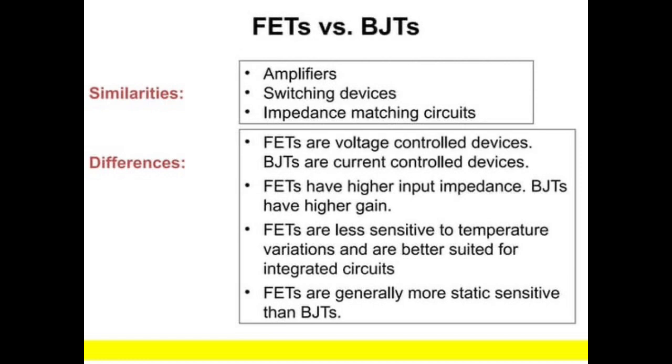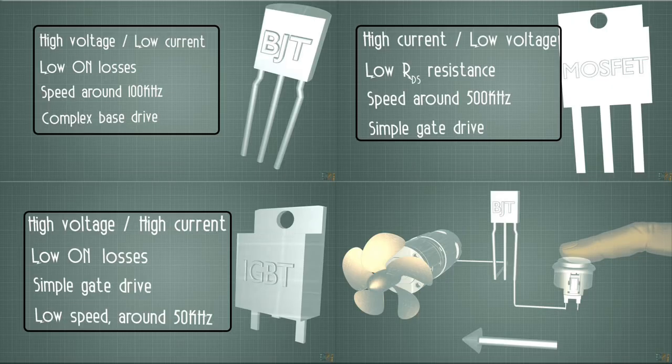Second is electrical properties. Silicon has a higher breakdown voltage and lower leakage current, making it more reliable in high voltage applications. Its oxide forms a stable insulating layer, which is crucial for manufacturing processes like passivation and integrated circuits. Third is availability and cost. Silicon is abundant, being the second most common element in the Earth's crust, and cheaper to process than germanium. The semiconductor industry has optimized silicon fabrication techniques over decades.